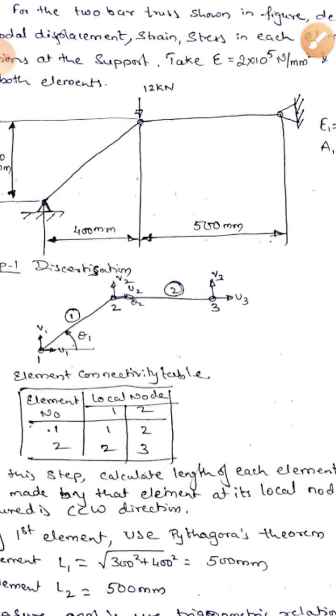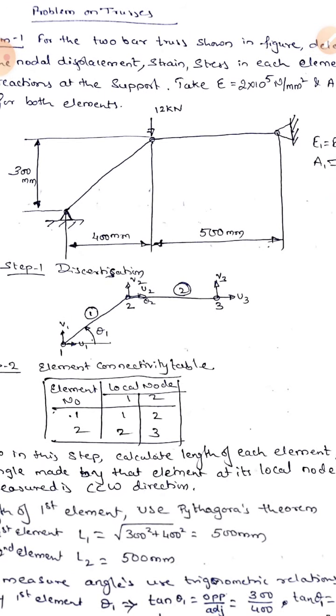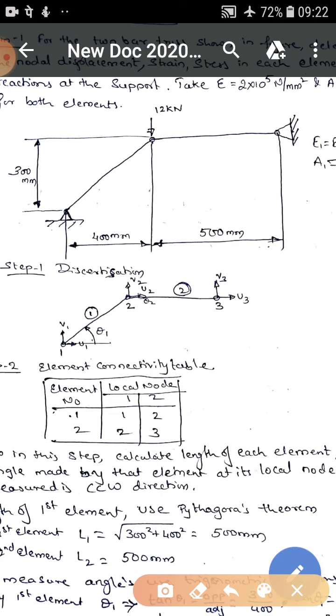This is the figure they have given you. Now from this you need to determine all the things that are necessary. See from the figure how the length of the element is given. There is one point that is fixed here, then there is an element, then another pin joint, then the element goes continuous, and there is a fixed end at the end. In this problem the first and last are totally fixed. The middle one is free, and the load is applied here. There are no forces applied at the other nodes.